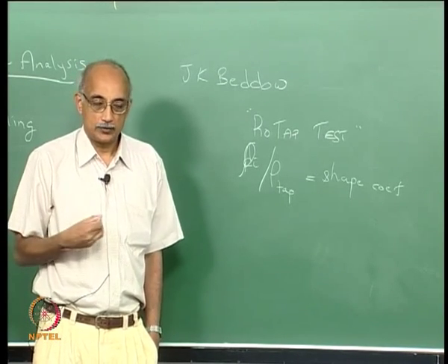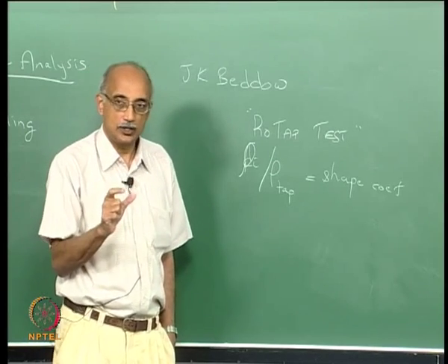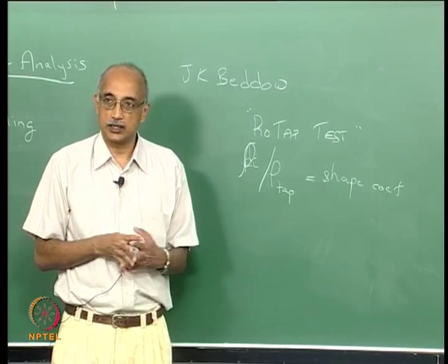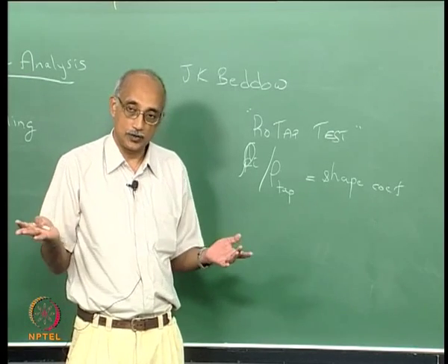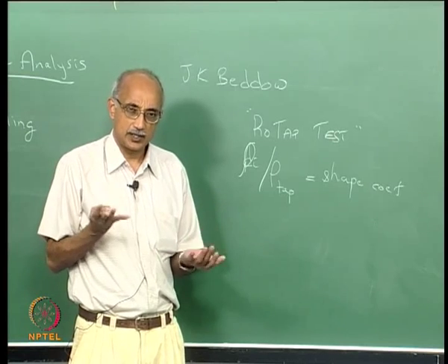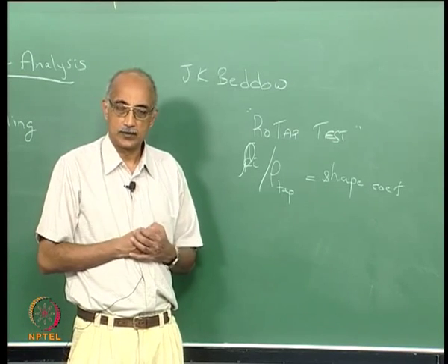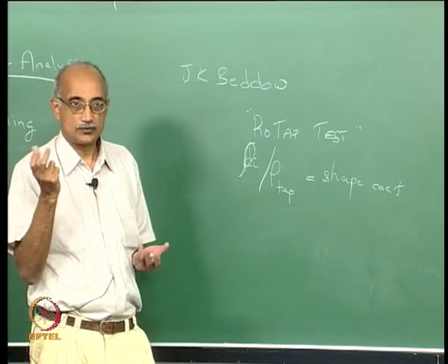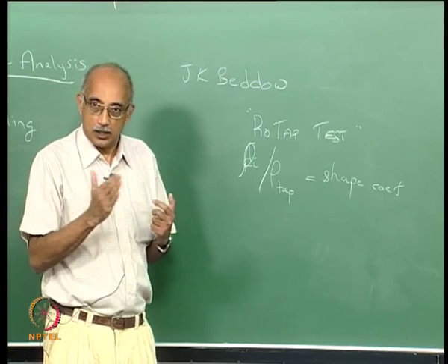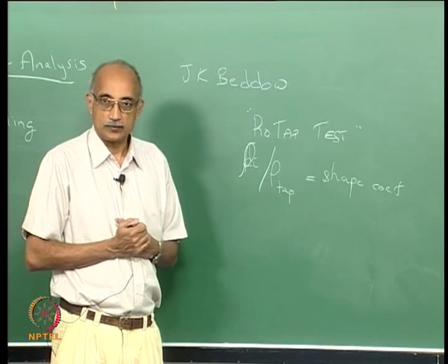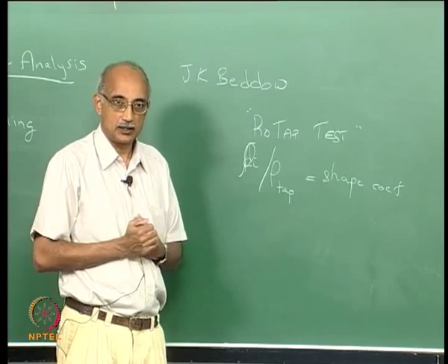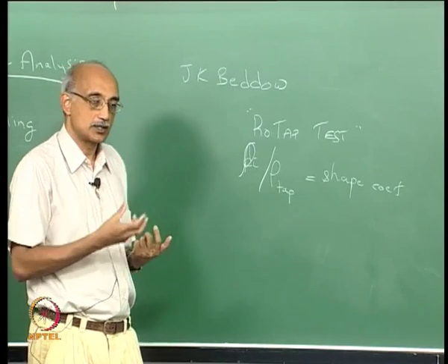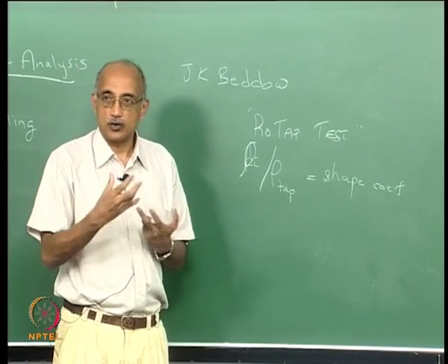Well, when you think about it, if you have a powder containing very regularly shaped and very uniformly shaped particles versus a powder that contains highly irregular and highly non-uniform shaped particles, their settling characteristics will be very different, right? You would expect that if you have a powder that's formulated with all smooth spherical particles and you tap it, what's going to happen to it? It's going to settle into a highly compact, almost sintered type of a powder. It's going to have very high density because the surfaces are going to be very conformal.